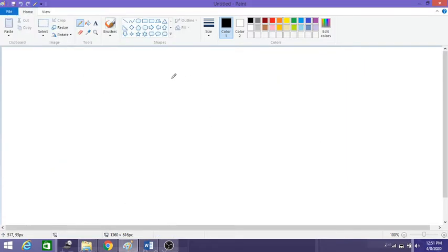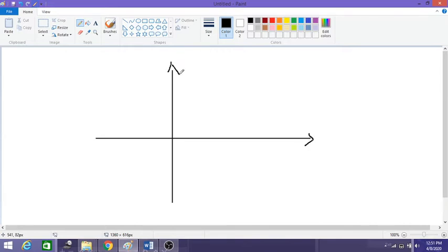So let us take the characteristic graph of SCR. So let me plot this characteristic graph. So this is V and this is I. The x-axis is the voltage and the y-axis is the current. Now as we increase the voltage without the gate current, it requires a very high anode to cathode voltage, and at some point maybe 300 volts or more than 300 volts is required to turn on the SCR.